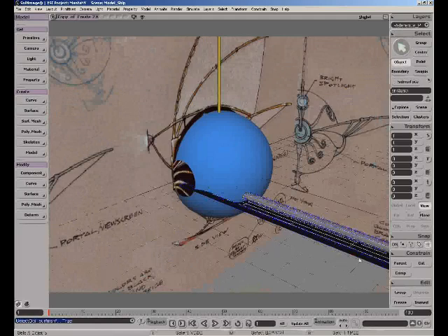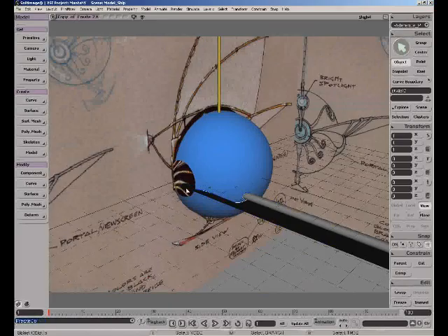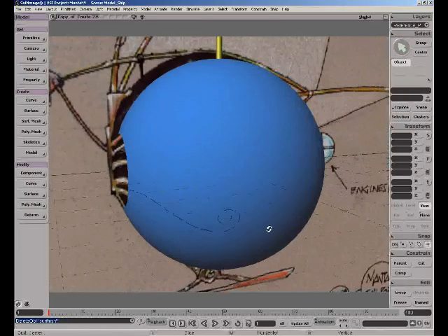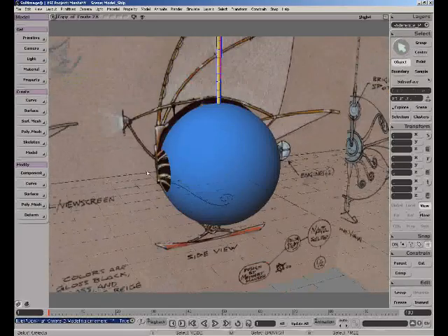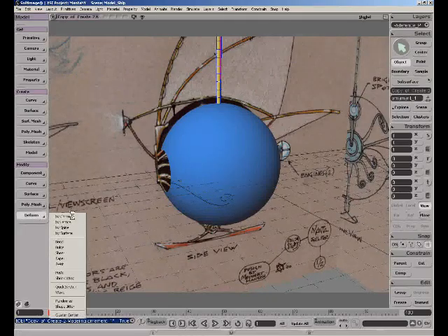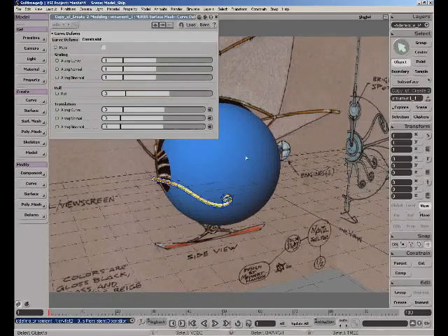So I'm going to go ahead now and just do a freeze operator on that curve. Select that curve and just click the freeze button. What that does is lock the relational modeling, and now this curve is locked. I can go ahead and delete this, and now you can see again right along that surface is that nice smooth curve. So now to make this object form on that, very simple. Select the object and just say deform by the curve, and then click on the curve that you want to deform it to. So let's go ahead and zoom in on this.